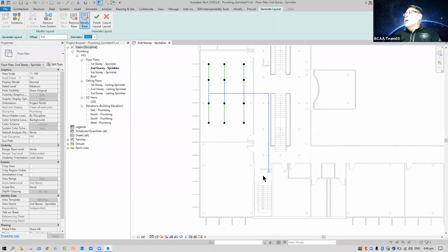Because let's say every zone has a different set, maybe also 2 to 3 pumps. I've got zone 1, zone 2, zone 3. So zone 1, the pump will be activated. So most likely I have 3 pumps here. Since it's separated into 3 zones, of course the pump capacity will be different, right? Sometimes you use 1 pump for the whole level, then it's a different story.